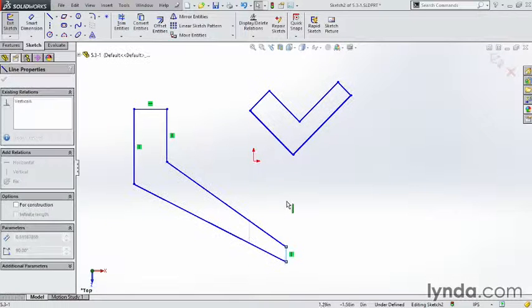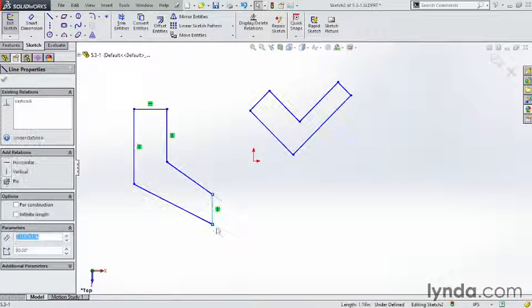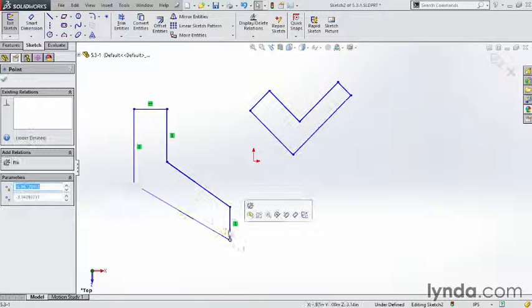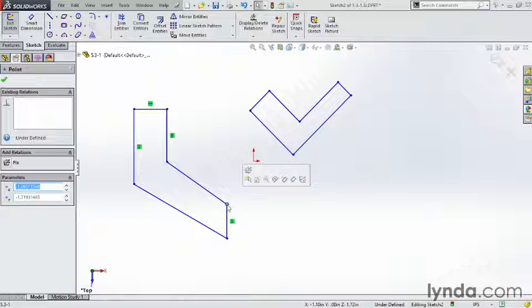Same thing though, you could actually do with moving things like this. By clicking on a point or dragging things like this, it just changes the different values, but it allows it all to change at the same scale factor. These tools focus on working with existing sketches and making sketch-wide changes. If modifying individual elements, it's probably just better to work with the constraining relationships to get the shape that you're looking for.